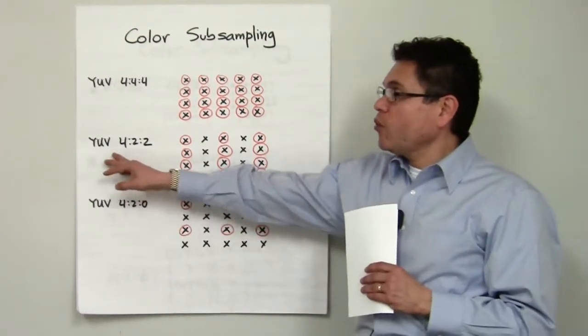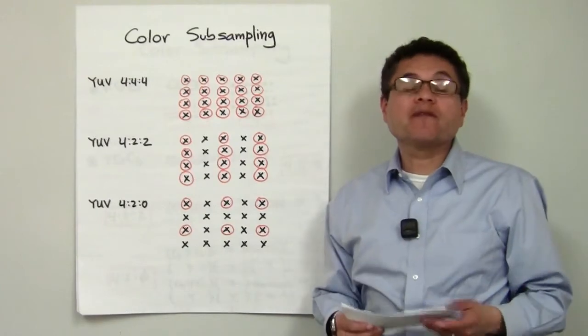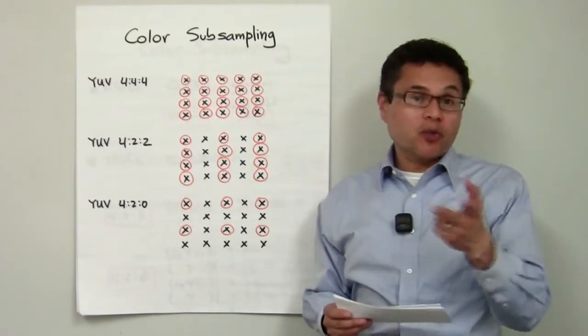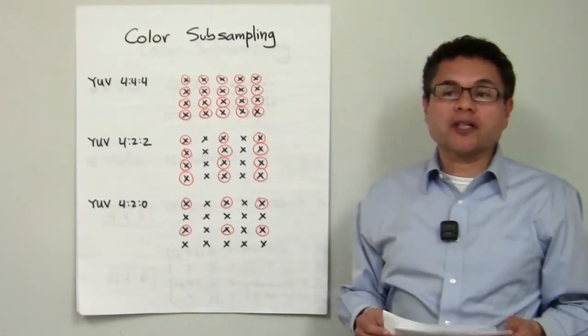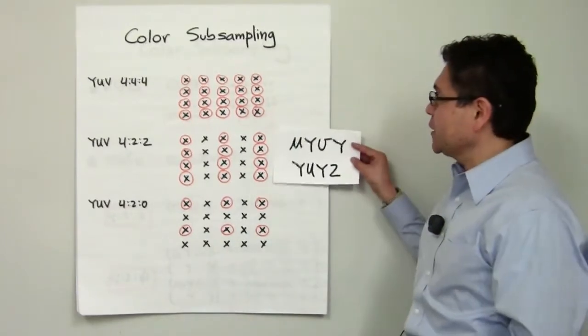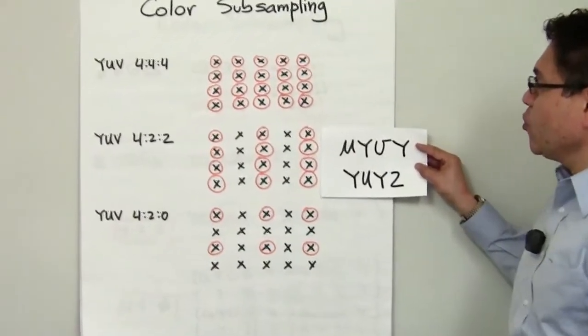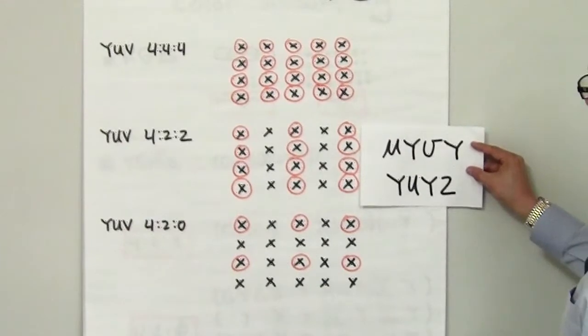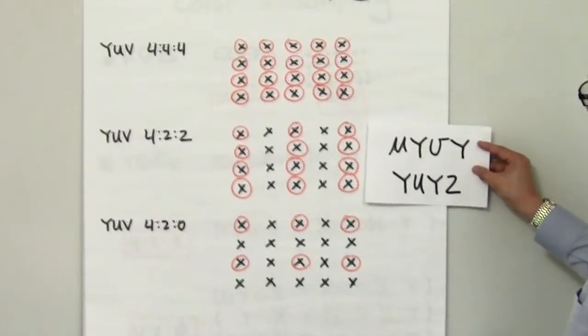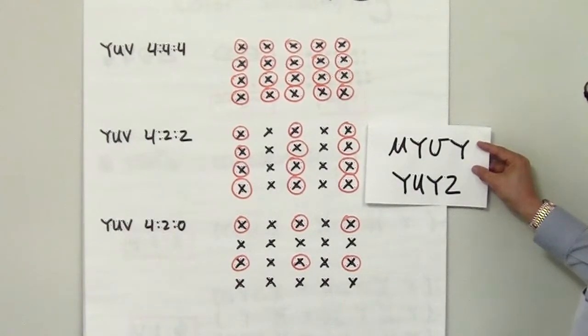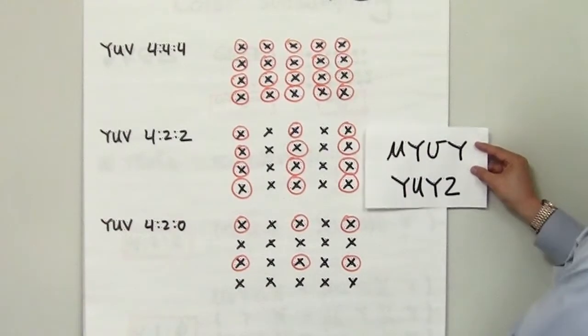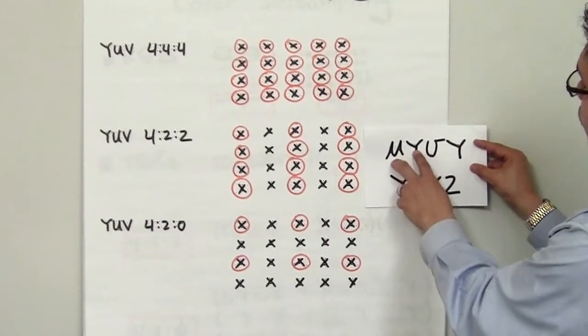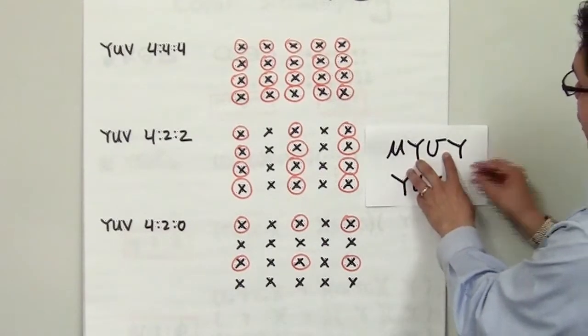So for the YUV422 subsampling, for instance, there are two very common 4cc codes that are used. One of them is the so-called UYVY code, which essentially indicates the exact subsampling of the chrominance components, where the U and V components belong to a Y, and there's a Y without any other chrominance.